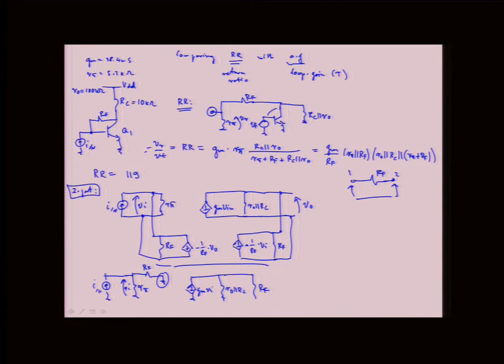And then again, because it's shunt at the input, I treat that as a voltage at the input feeding through the feedback network. So I need to disable that when I'm looking from the output. So you ground when shunt, and then here it's also shunt, right?